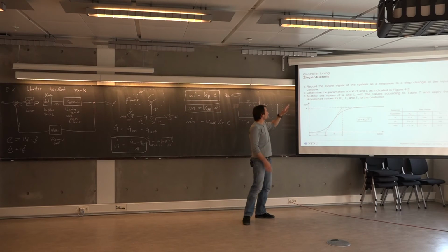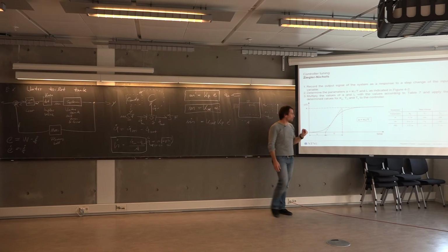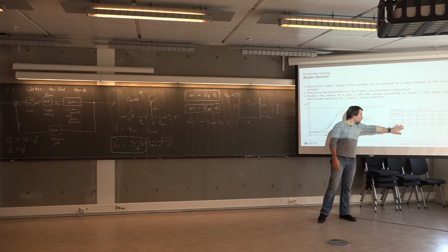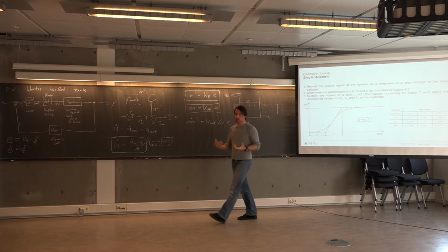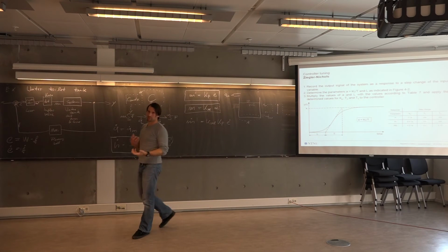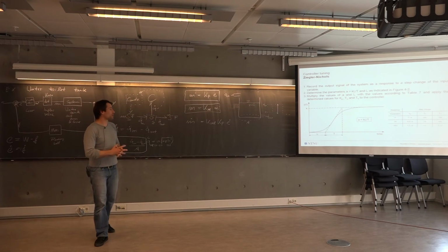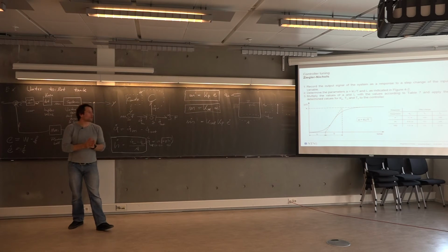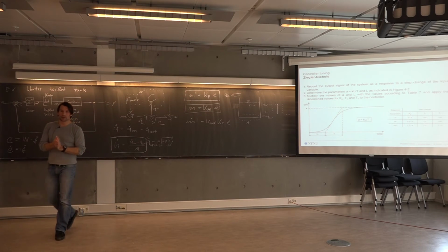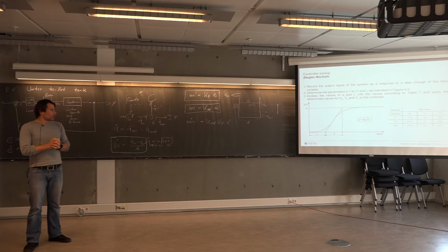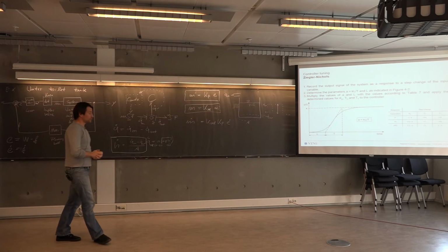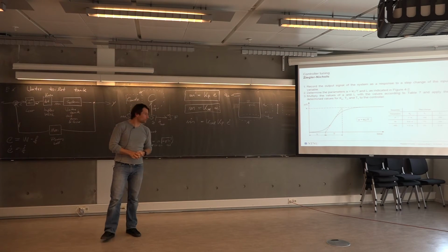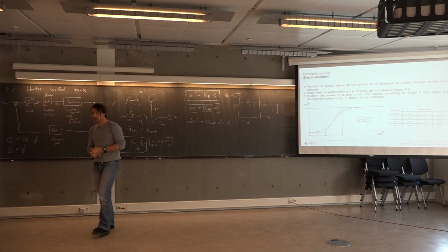And then, and this is the concept of these guys, Ziegler-Nichols, you use these empirical formulas to compute, let's say, fairly good numerical values for the PID or the PI or the P regulator. This is one way to obtain numerical values for these various controllers. There are other ways.